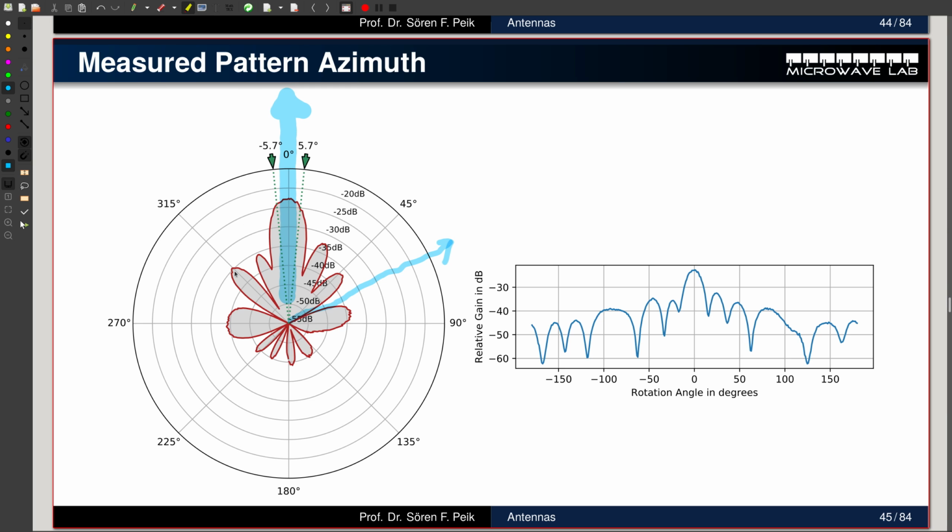And then at other directions, you see, interestingly, for example in this direction, 315 degrees. That's my azimuth pattern. You see that you radiate minus 35 dB compared to the minus 22 dB here. Still a reasonable amount of power you radiate from these so-called side lobes. That's very typical for antennas. It happens from the field theory that you have a number of side lobes where it radiates even though you don't want it, but that's a fact of life you cannot avoid.